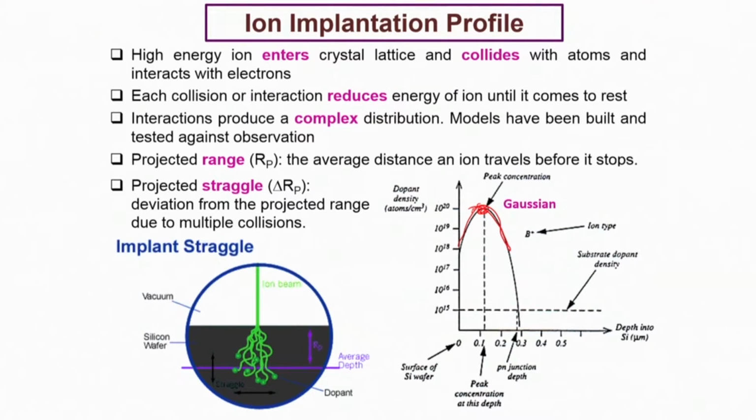So that kind of implantation process allows implantation of the species to be concentrated and to reach a maximum concentration, not at the surface but below the surface, somewhere here. So the design of the process has to be done properly, so that we know exactly what would be the concentration of the species below the surface.